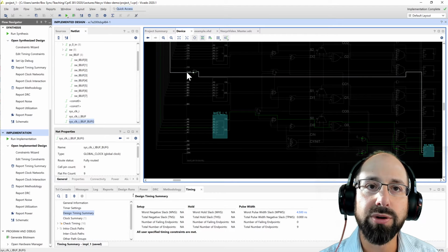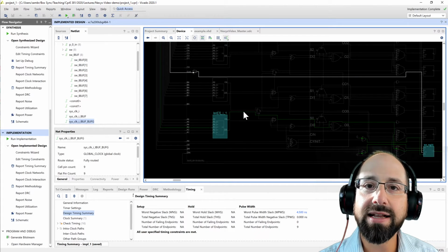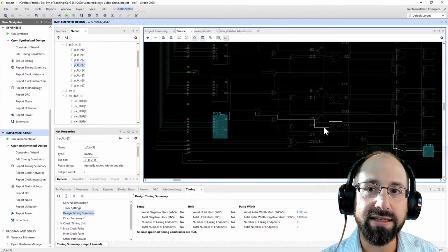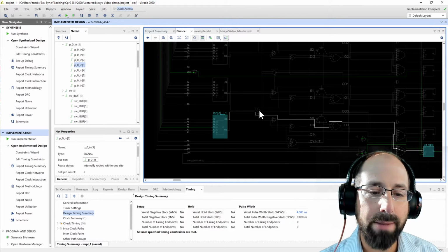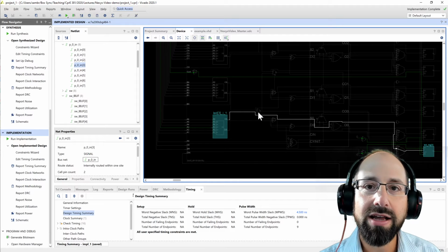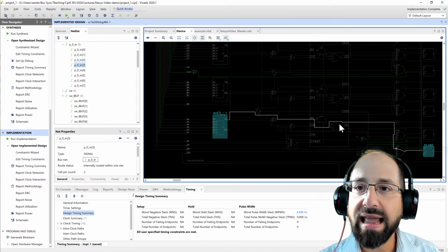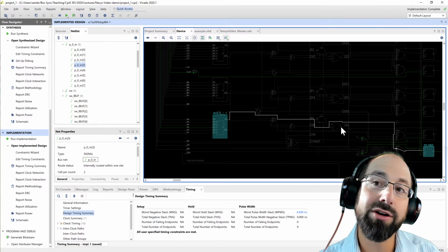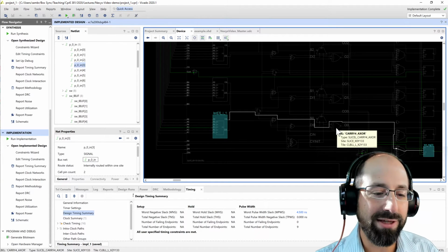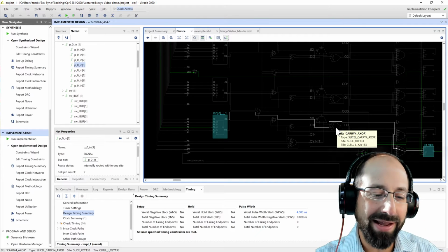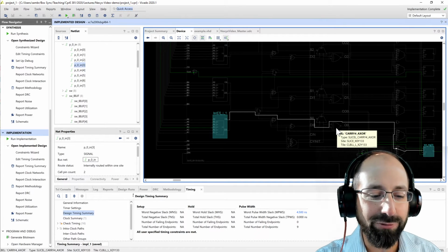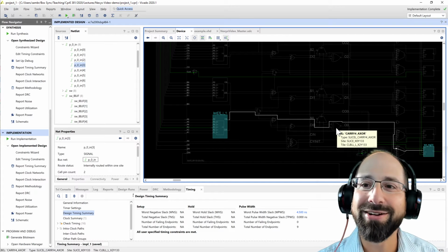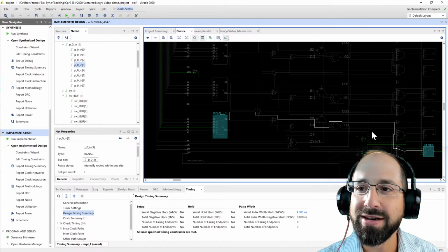We also have our input clock that's getting routed in, and we can kind of see what's happening here, right? This is traveling through a lot of logic that it's basically circumventing. So I'm positive you can't see that at all right now. But those are little muxes, and there's an XOR gate here that's labeled as carry chain, which if you take 583, you'll see the connection back to 381 as to why FPGAs have little XOR gates hard coded in the design specifically for carry chains. We'll even talk a little bit about that on Monday potentially.